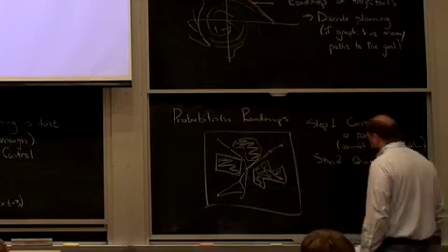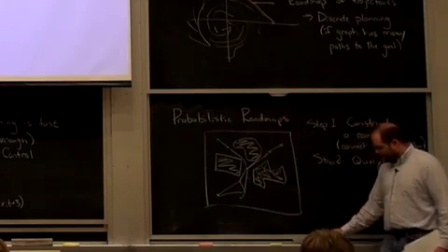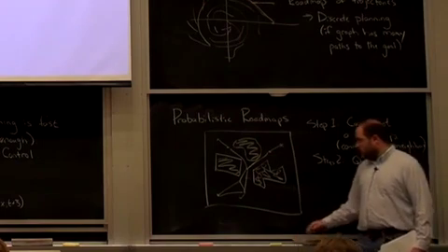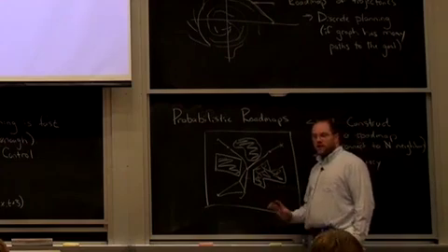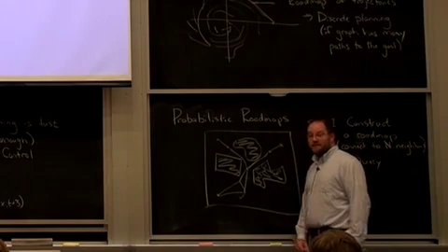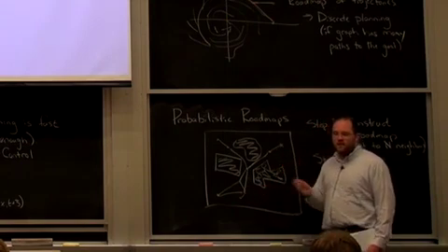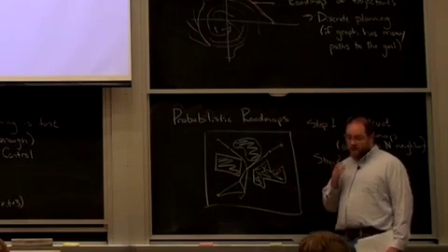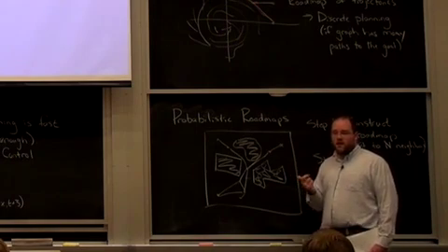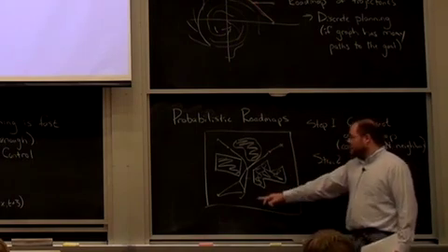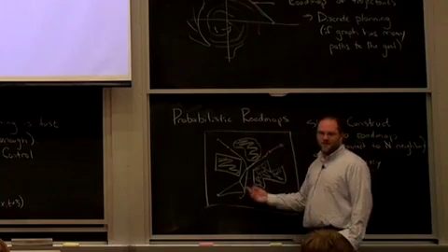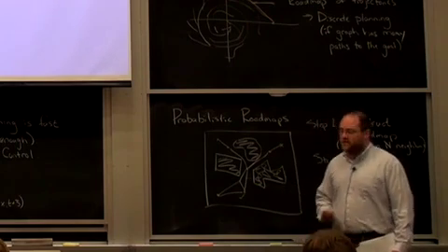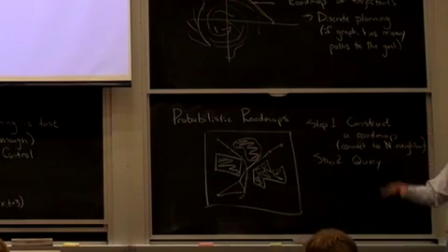Given a rich enough roadmap, would you have problems choosing the best path from among those paths? So, discrete search. The discrete search, I think, in general, you should think of as being basically unlimited. Compared to all these continuous time methods, it's very, very efficient, right? People do it on huge collections of nodes very efficiently, especially if you can do sort of A*, if you find a good heuristic. To maybe overplay the title, this is how you go to MapQuest and you ask it to go from Boston to California and it just happens, right? These things are very fast, even with a lot of nodes, a lot of roads.